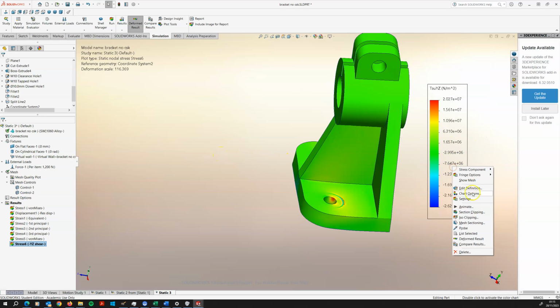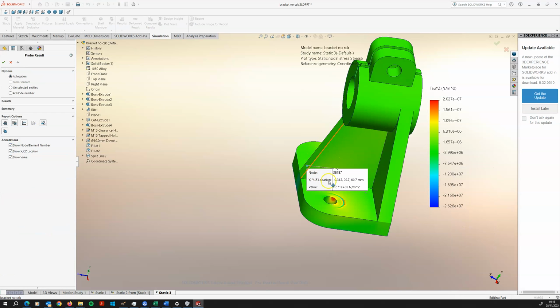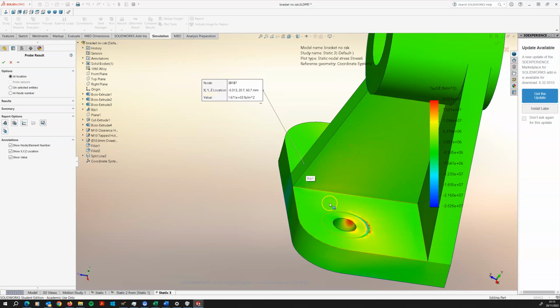So along the rib there, that would be actually very low. It's almost zero perpendicular to that rib there. But if you come back a little bit away from that, it's about 2 megapascals there. 3.5 megapascals there. So it's like shear stress in bending, where the shear stress is zero at the surface, but it gets bigger as you go away from the surface.